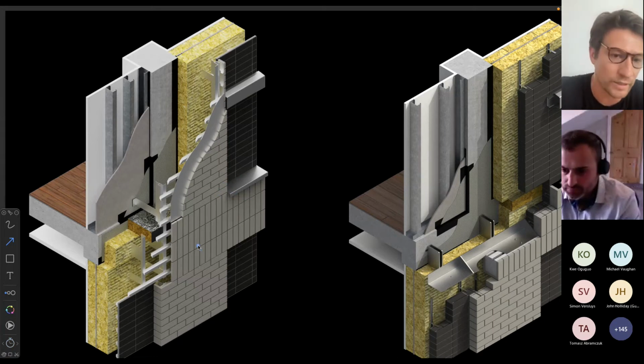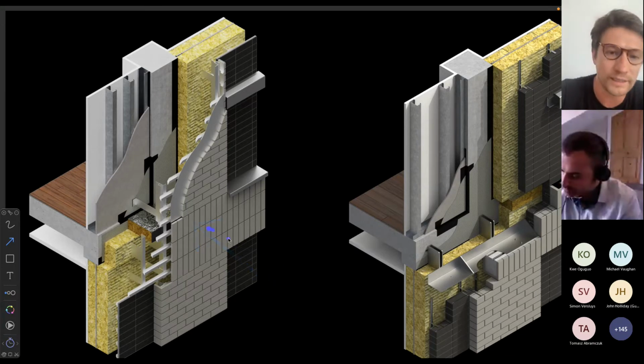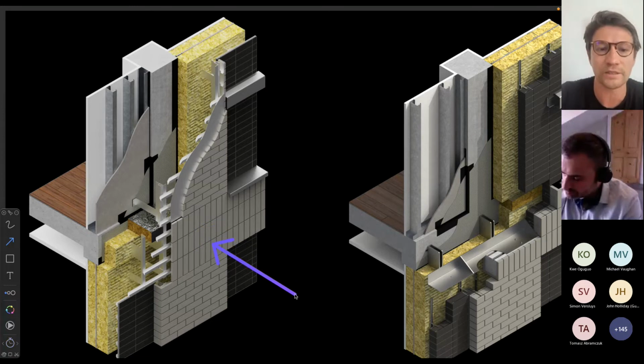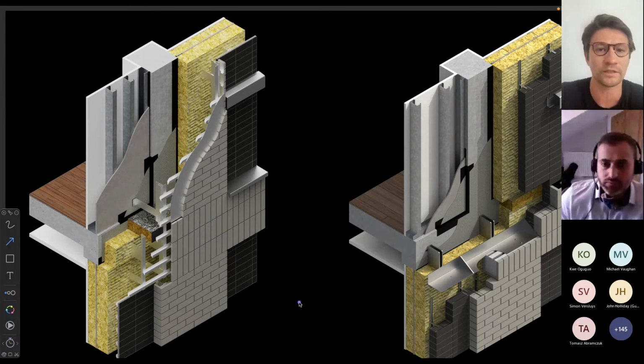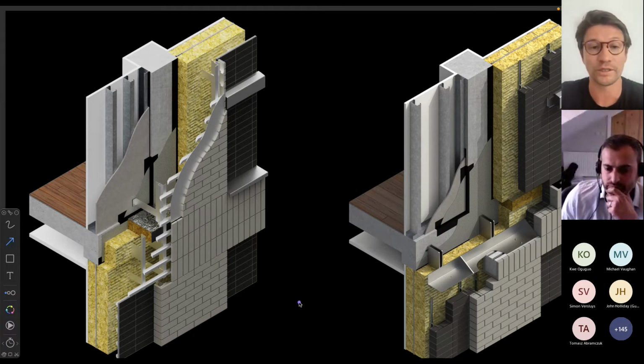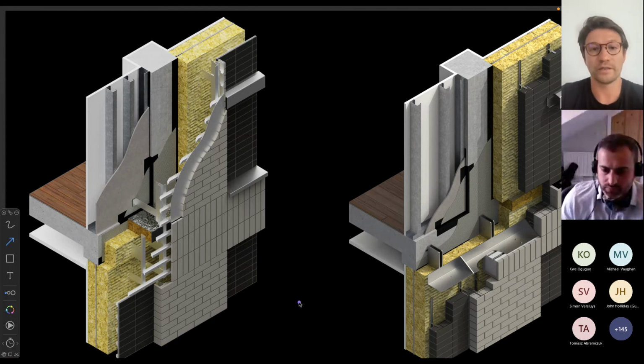So I would not see brick slips cladding used in this detail any different to aluminium cladding or terracotta cladding or any type of rain screen cladding. I would treat it exactly the same as just a veneer of the facade, and everything else performance-wise would be treated as an aluminium cladding building. I'm not sure if that answered the question.